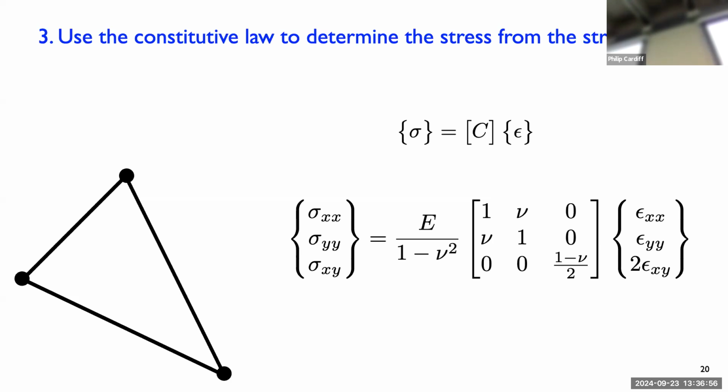We had that before, but now we also have a mu in the YY direction. So it means that even if the strain in the XX direction is 0, you will still get a stress in the XX direction if the YY strain is non-zero. So if I'm holding something at a constant length, and someone else is pushing or pulling in the perpendicular direction, that will generate stress in the direction I'm pulling it. So that's this 3D effect, this Poisson effect.